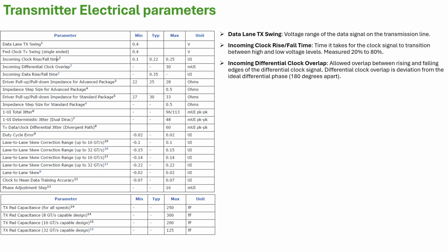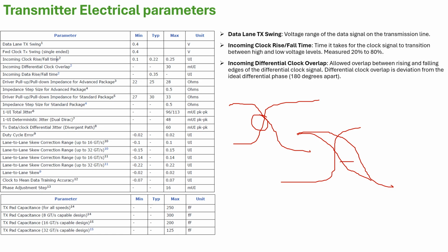It means these are differential signals, right? At some time both transistors will be on. There's overlap in between. Another thing is slew also. For example, you have this positive signal coming here, clock, and here this can be an overlap. Second thing is, for example, this is one, right? I'm supposed to come here, but it comes here a little bit delayed. So for some moment both are on.